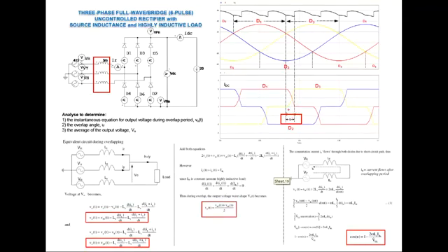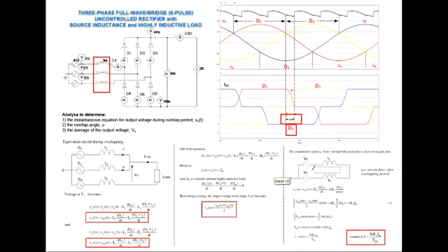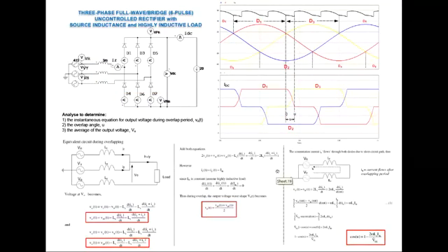During this time, diode D2 also operates. So we have D1 and D3, as well as D2 in the bottom group, operating during the transition. Because of that overlap, the output voltage no longer has the usual 6-pass waveform.